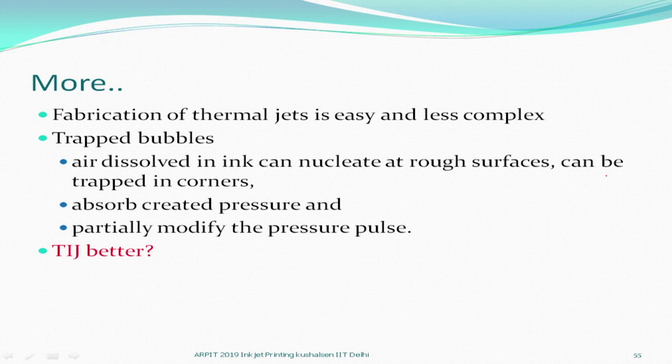If somebody wants to know, well, this question has to be answered not in this way, but if you want to use pigment based inks, which normally may have a binder in their composition, then you may not like to use a thermal inkjet system, because this increase in temperature can help polymerize the binder, and so the nozzles can get choked, viscosities can change, and so on and so forth. But otherwise, yes, it is good.